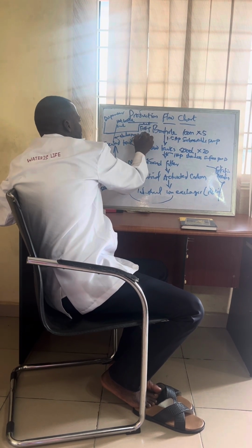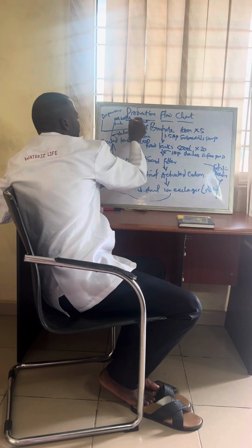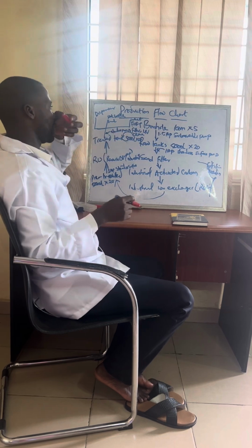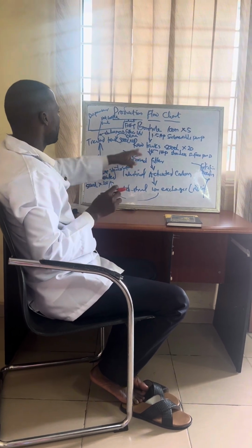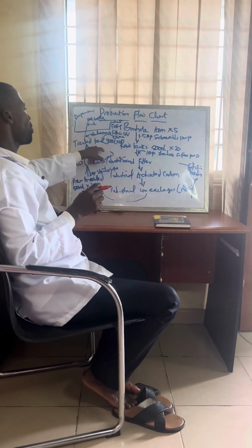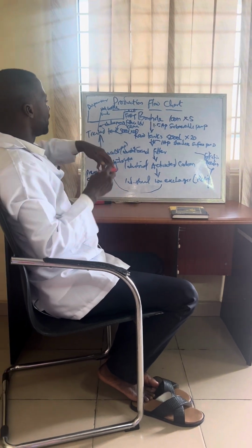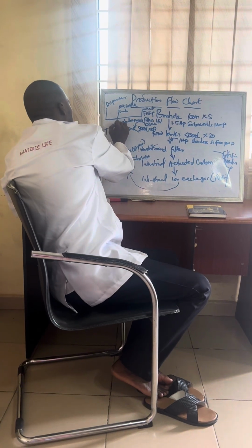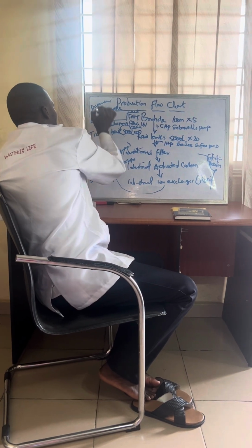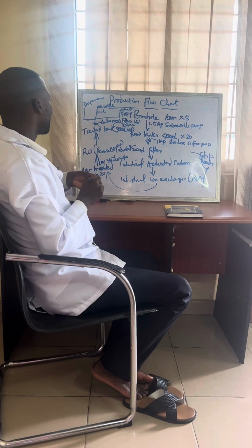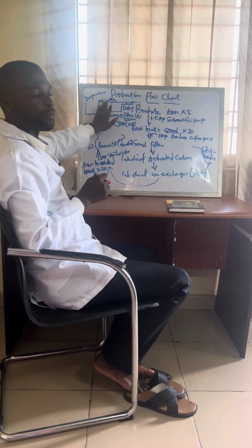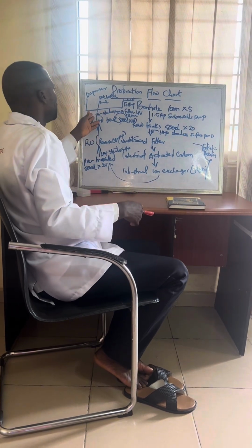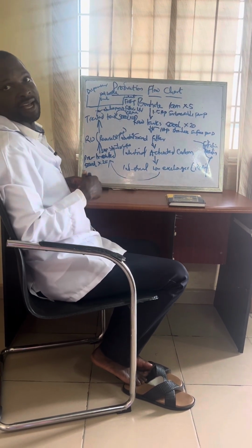There are also filters of different micron sizes, and there is a UV of this micron size. Like I told you, in some instances, your ozone is being dosed directly into the tank. In some instances, your ozone generator is infused into the system. That is, water from your treated tanks passes through the ozone compartment, and then there's a dosing before going to your sachet side, your PET bottle side, and your dispenser side.